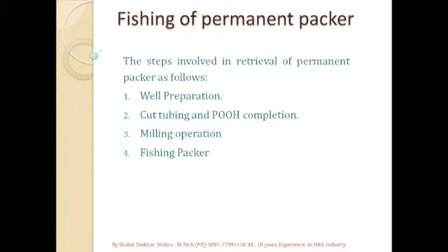Then if there is not enough rat hole, or we cannot push down due to some tailpipe or something below the packer, then we have to fish out. So after milling, we go for the fishing operation of the packer.